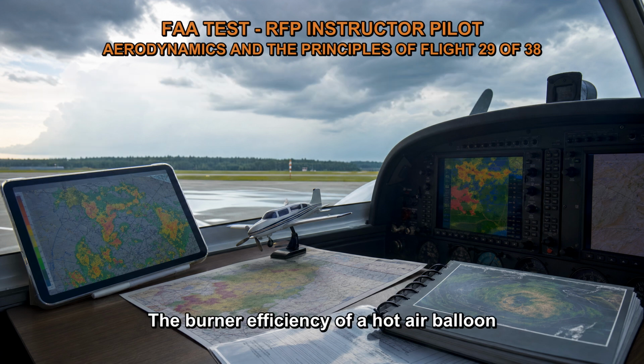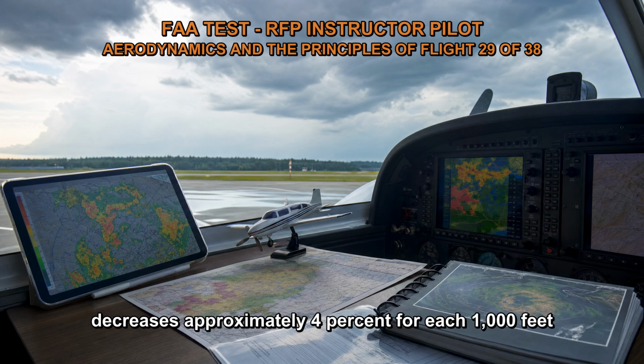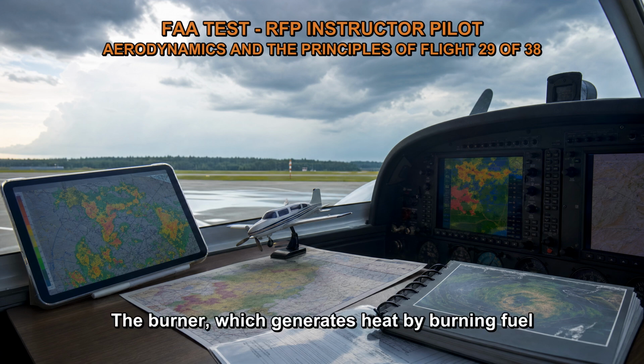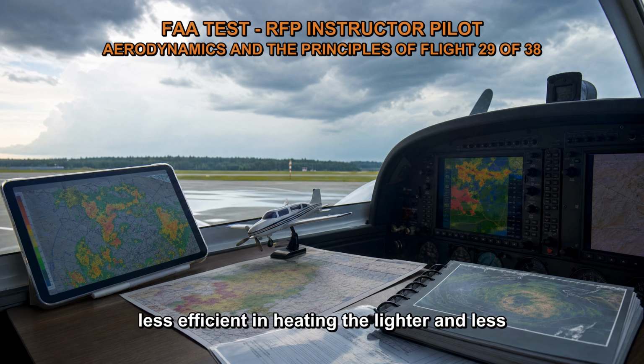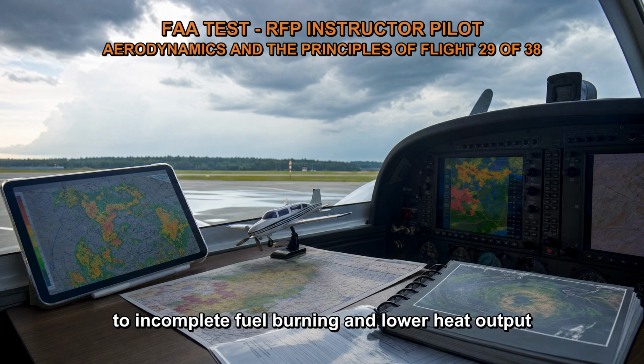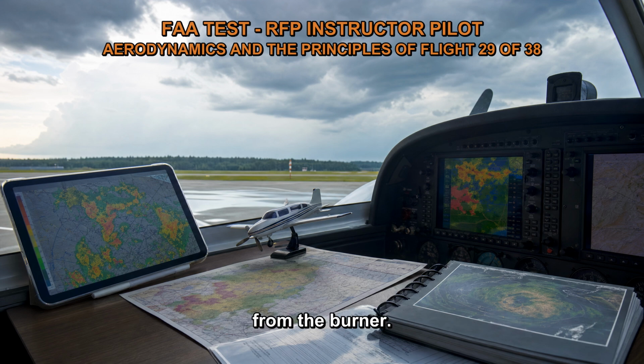The burner efficiency of a hot air balloon decreases approximately 4% for each 1,000 feet above mean sea level, MSL. As a hot air balloon ascends to higher altitudes, the air density decreases. The burner, which generates heat by burning fuel to heat the air inside the envelope, becomes less efficient in heating the lighter and less dense air. The decrease in air density at higher altitudes results in reduced oxygen supply for combustion, leading to incomplete fuel burning and lower heat output from the burner.